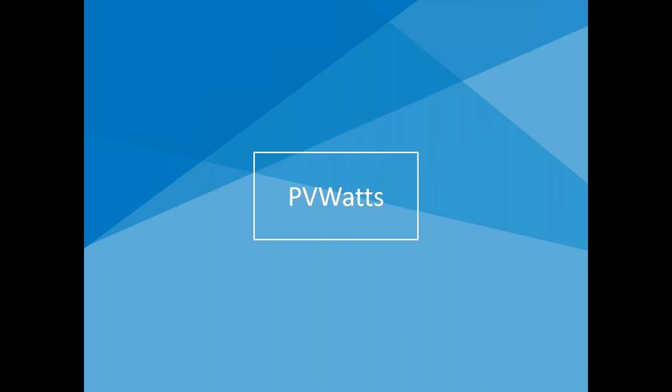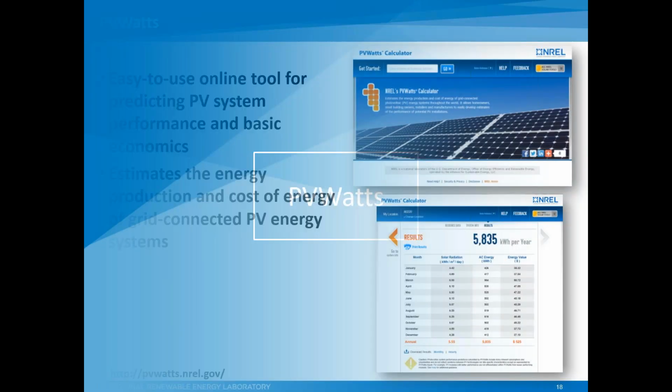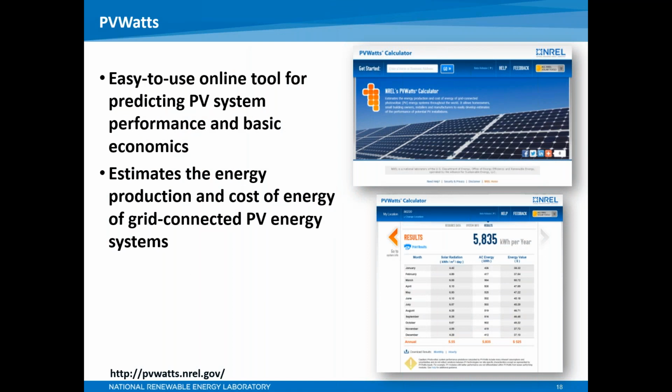And then getting into a couple of the tools that NREL has that I also think are really good. So I'm thinking, you start with the mapper, you identify a site, and then you go to the decision tree, and then you might want to use something like PVWatts, which is a free, again, downloadable tool at pvwatts.nrel.gov.